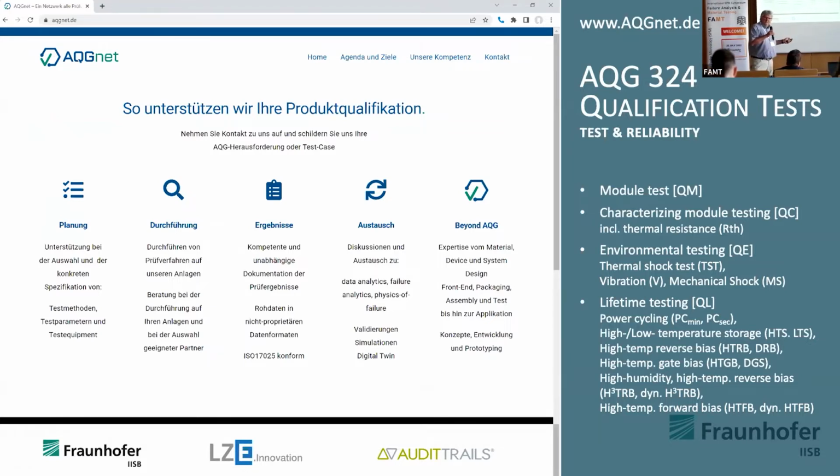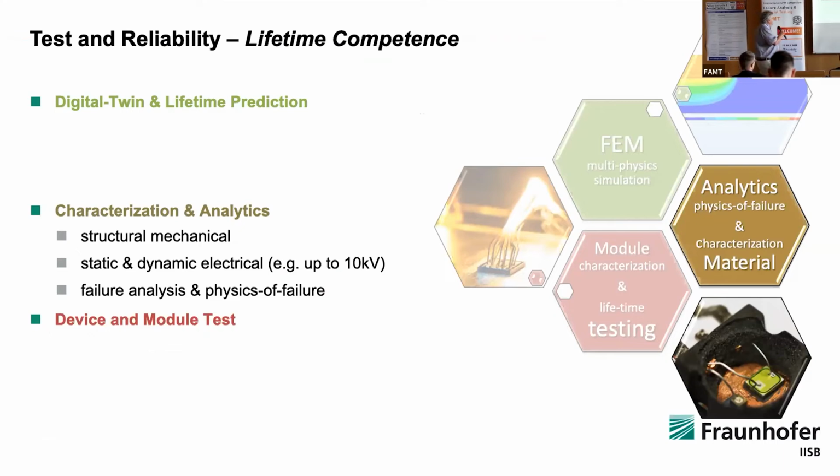we talked about degradation under voltage and current flow, bipolar degradation in silicon carbide devices. This would be then the macroscopic test for this high temperature gate stress test, dynamic gate stress test. So this is related to the stuff we discussed in analysis, and we do it on the macroscopic side, really stress the devices. The next one,